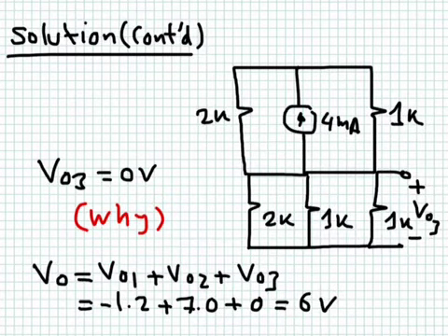So this is what we did here. I shorted the first voltage source. This is where the 12 volts used to be, and the 6 volts used to be here. They are both shorted. You have only the current source. Of course, in this case, if you see a current flowing here, this current will continue this way because it's a short circuit between here and here. So there is no current flowing in this lower resistance.